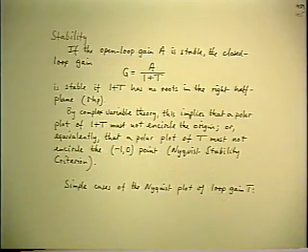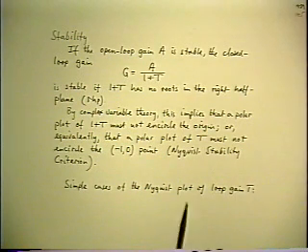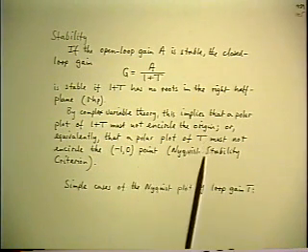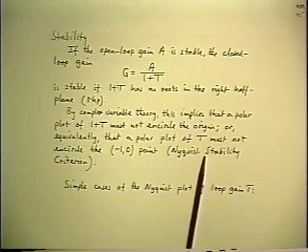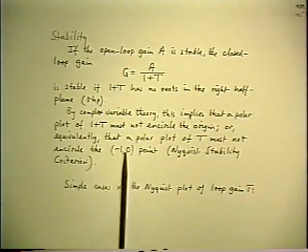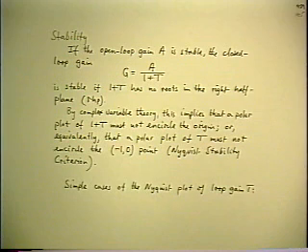That's obviously the same thing, just shifting the effective origin by 1 unit. And it's in that form that you normally see the Nyquist stability criterion. The polar plot of T must not encircle the -1 point. So that's in all the books. What you don't find in so many books is what polar plots really look like for some useful cases. So let's talk about that.